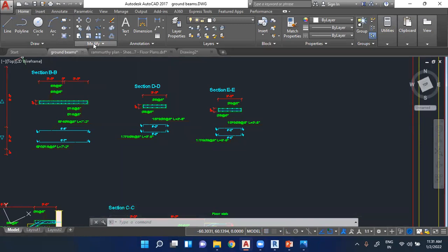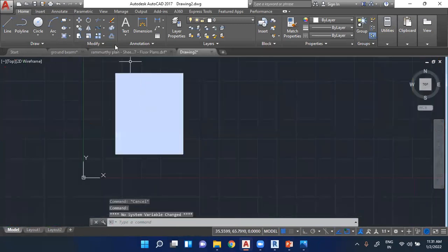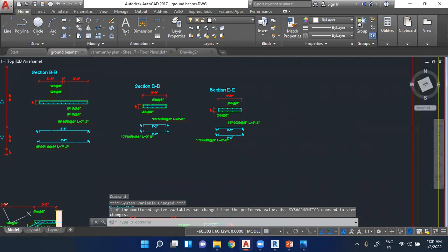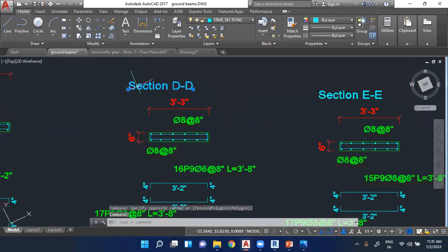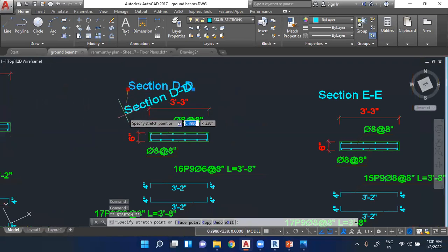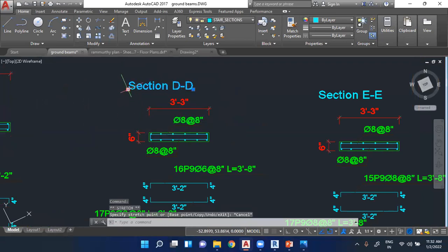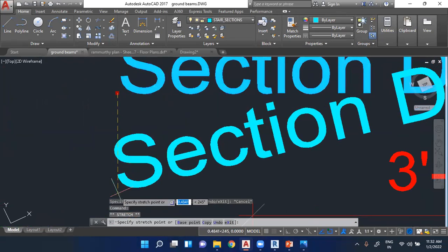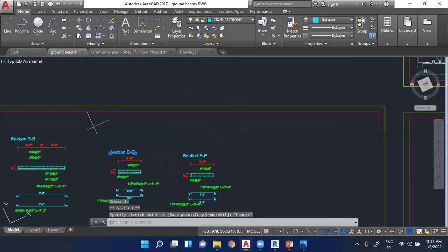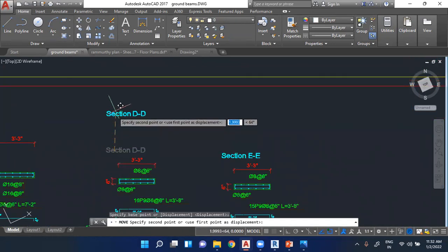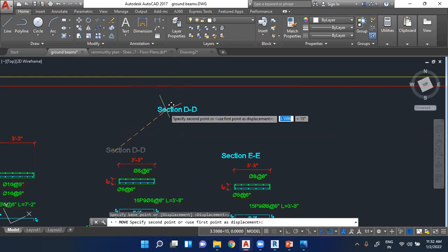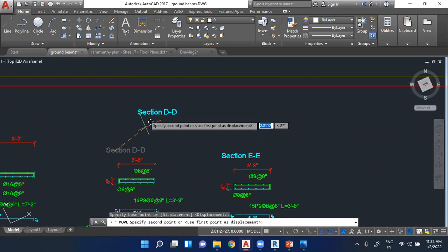And when I want these drawings to be modified, I'll come to this modify section, and when I want this to be moved, there are 2 options. I can click here and click on the boxes that are showing, and I can move these, or I can just click on the move tool by selecting this, and I can move this to any position in the AutoCAD world.